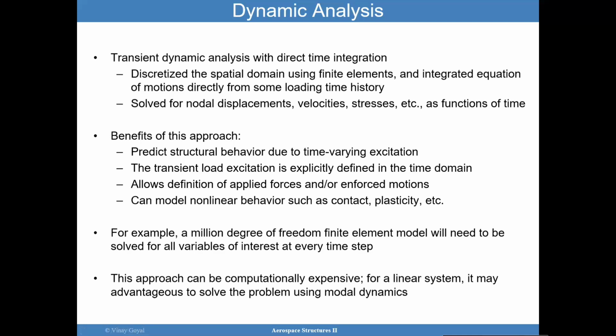The transient load excitation is explicitly defined in the time domain. It allows for definitions of applied forces and enforced motions. You can also model nonlinear behaviors, contact, plasticity, and so forth. But if you had 1,000,000 degrees of freedom, it's going to be very tough to really solve that for every single time step. This approach can be computationally expensive, very expensive, even for a linear system.